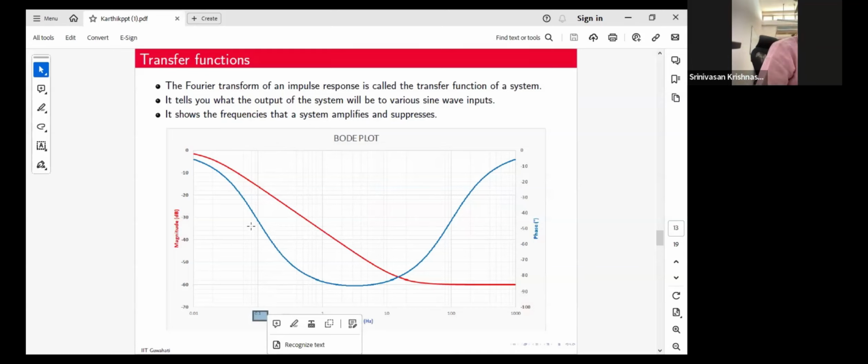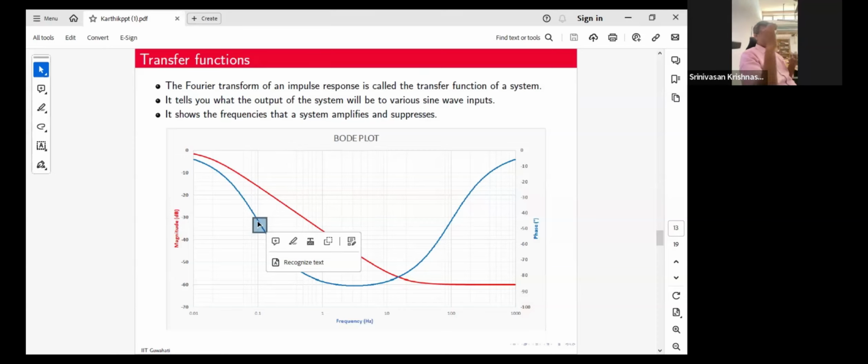And the second important thing is you have this phase that you see here, which means that you have a phase delay of 30 degrees, which means that your output signal will deviate from the input signal by an amount of 30 degrees. That means your signal would be delayed at the output, which defines how much delay that signal will have at the output. So you have a signal that's going to be attenuated by minus 14 decibels, and a delay of minus 30 degrees.